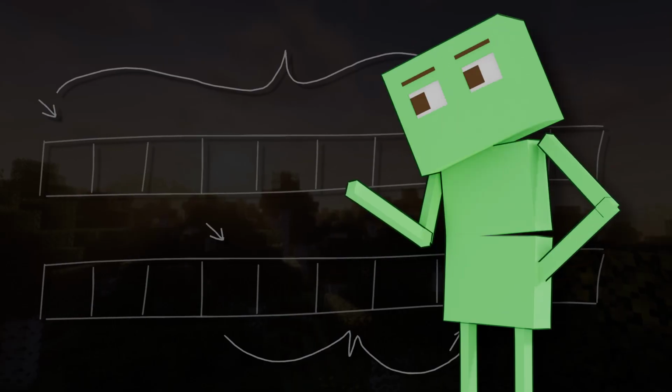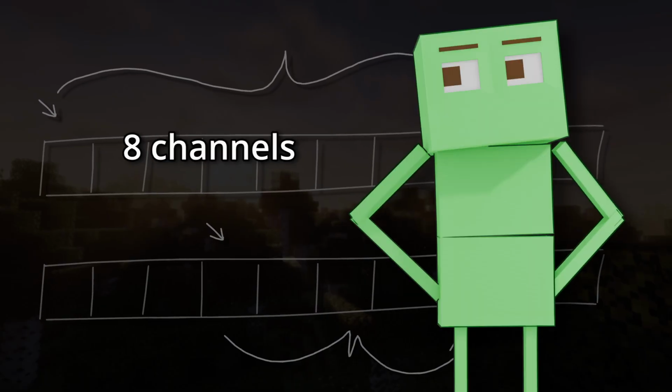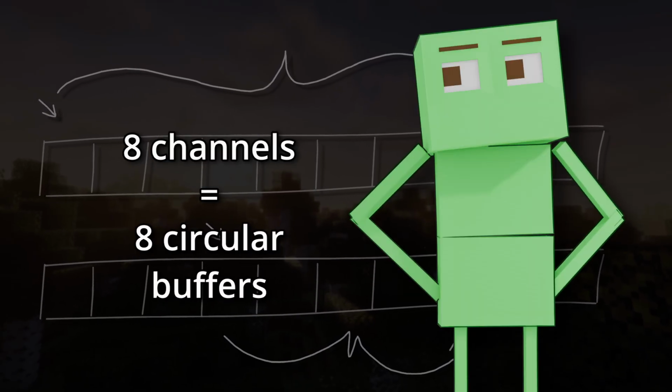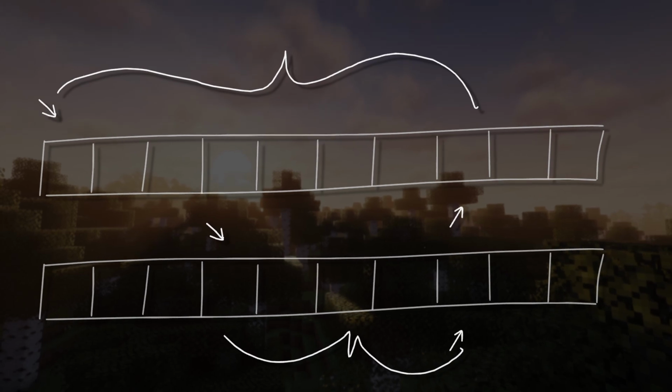And so yes, because we now have more channels, we also need a circular buffer for each channel. If we had 8 channels of delay/echoes, we need 8 circular buffers, which does sound like a lot of memory, but you also do have a choice of how big you want the buffer to be in the first place. We're gonna use 2 times the sampling rate as the size of our circular buffer for each channel. That way we always have 2 seconds of data just in the buffer because, you know, the sample rate is 1 second, 2 times sample rate, you get it.